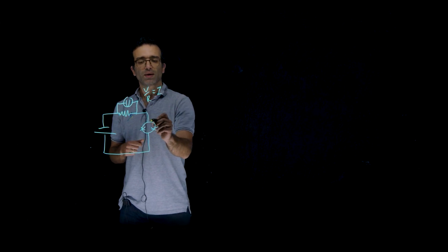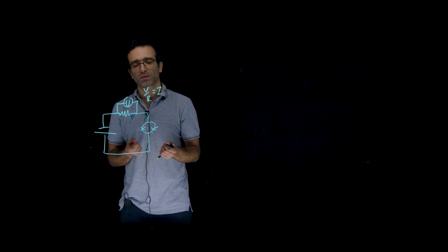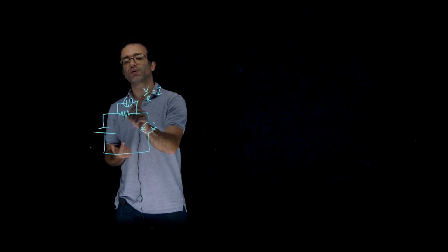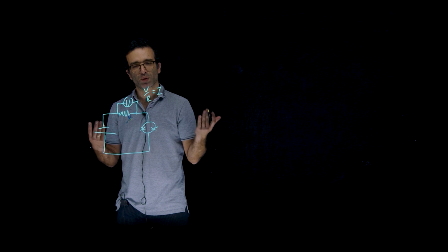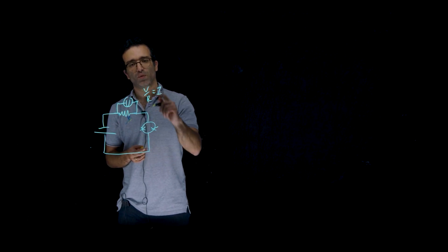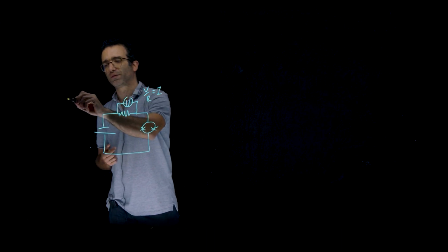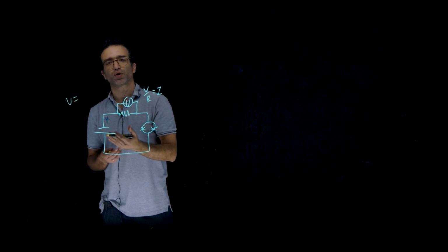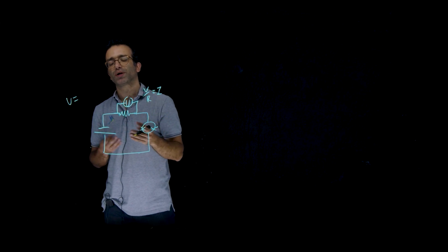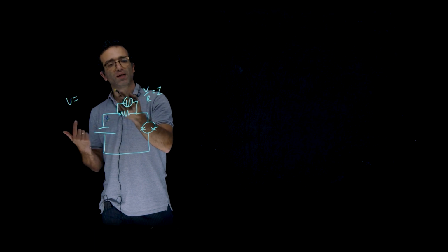Why is that? The resistance here, even in the normal state, is typically very small, of the order of an ohm or something like that. If you want a good readout, let's say what I'm measuring here is V, and I can measure to 1 microvolt, and I want to be able to measure a nanoamp, so I would need to put a kilo ohm, right?